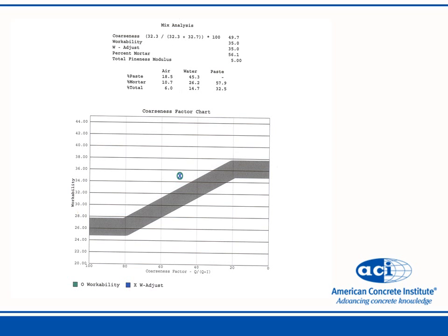Then I would include a chart with the coarseness factor and workability, because the engineers were going to have to learn in years to come about a coarseness factor chart and a workability. So I would include this with the mix design submittal as part of my computer generated mix design and what it looks like using a computer.